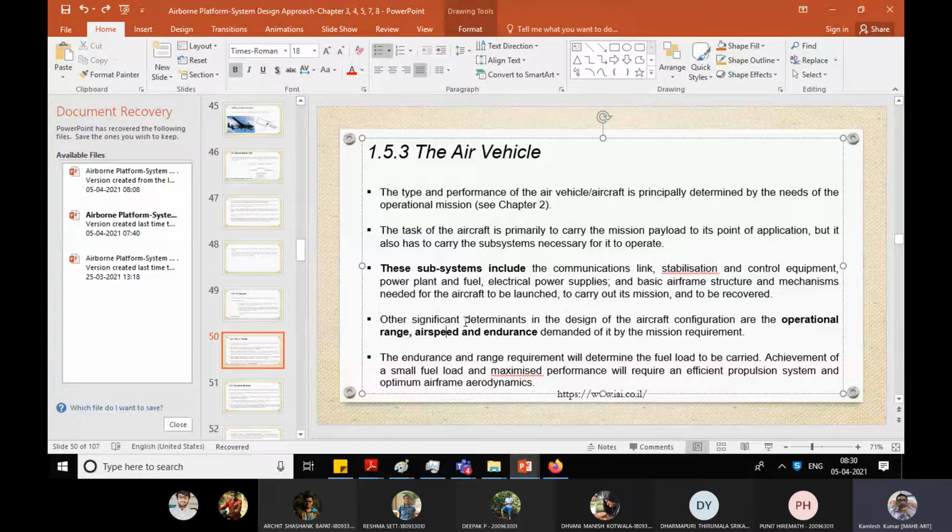If you know only maximum, then there is no good idea, correct? Maximum is just recommended for achieving long range. Okay, and already you know that maybe lift generation is not creating a problem, correct? Because of the high speed, but minimum speed is also important. It should not affect the lift generation, because minimum airspeed means minimum lift should be generated which can balance the aircraft weight, correct, including the payload. So of course we are talking about the flight envelope for the airspeed.